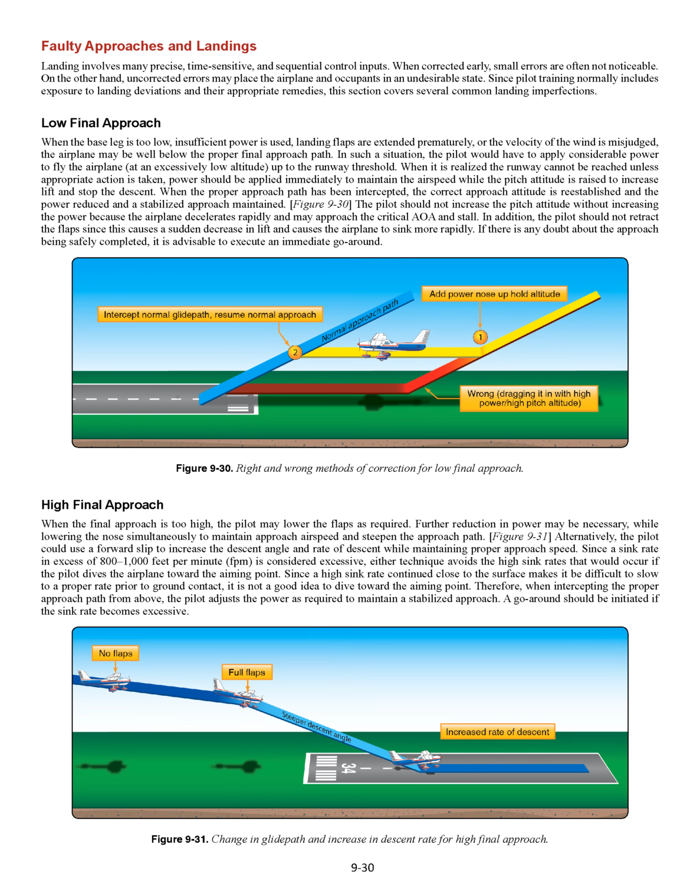In addition, the pilot should not retract the flaps, since this causes a sudden decrease in lift and causes the airplane to sink more rapidly. If there is any doubt about the approach being safely completed, it is advisable to execute an immediate go-around.